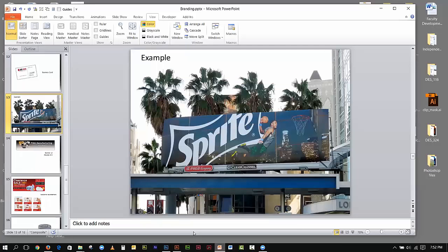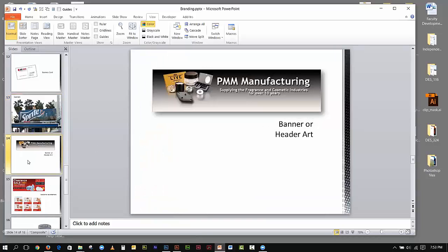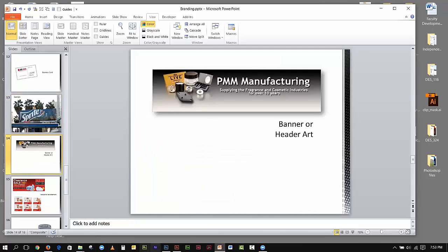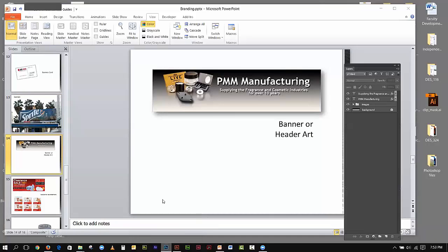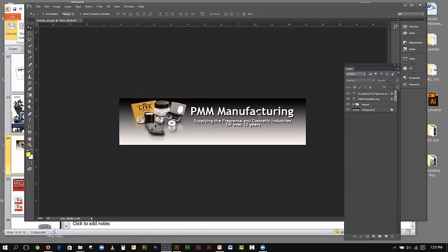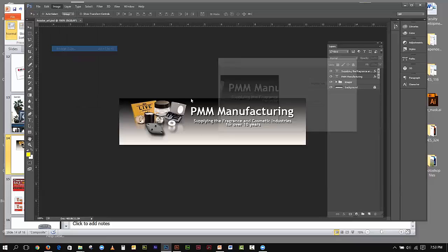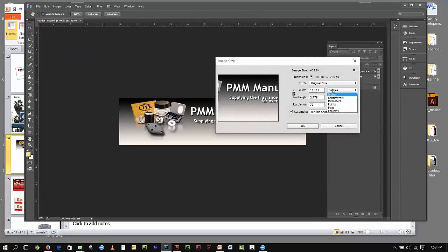So let's go back to here. That's your billboard. Now, the other thing I have here is a banner art or header art. I got a couple of pieces here. These are web banners, web banner advertisements, and this is a piece of header art. First of all, what I did with the header art was this is a header for a website. This was not the one that was used, but it's the one that I thought was kind of interesting to look at. If you go to Image Size, you'll see that this is set to inches, but I'm going to change it to pixels.